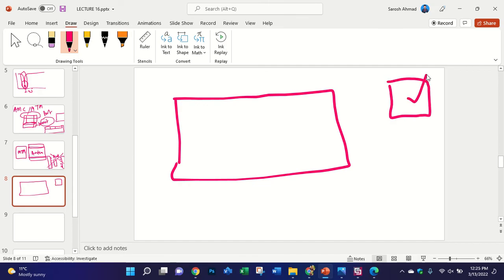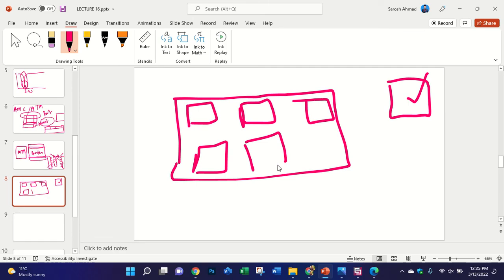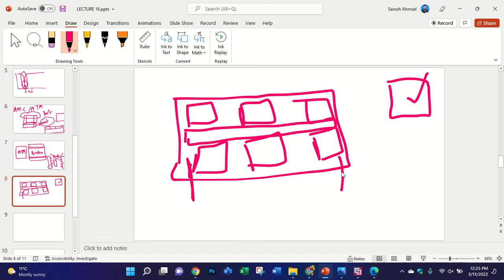Suppose you have designed the EBG unit cell, then you convert it into arrays, and then sometimes you create a strip line of the same size as this length, and then you create a port here